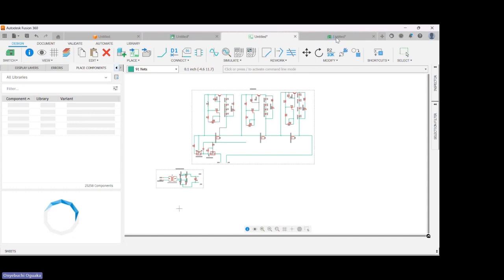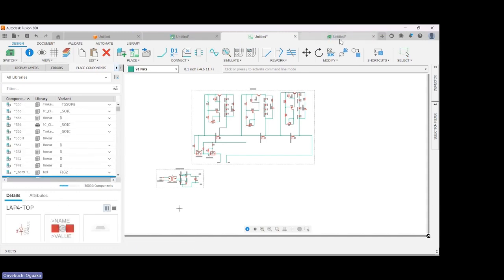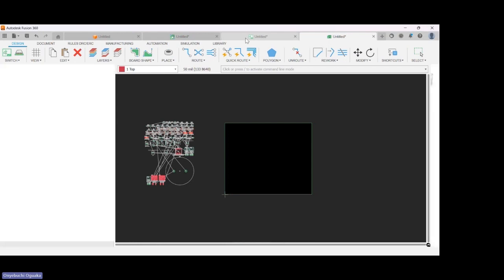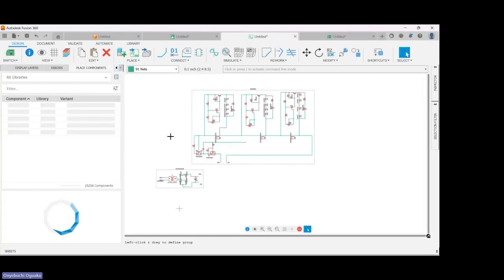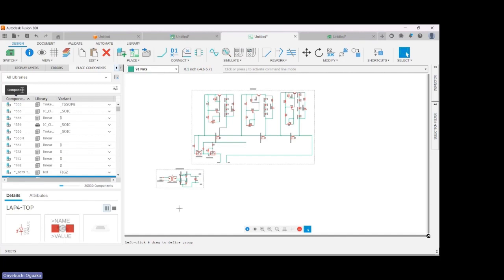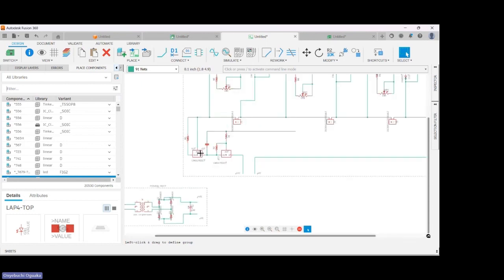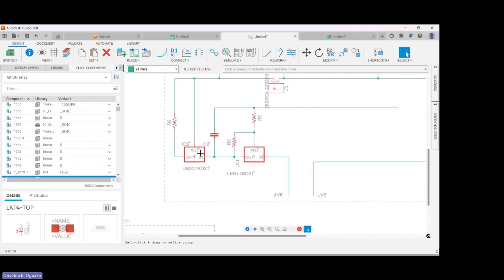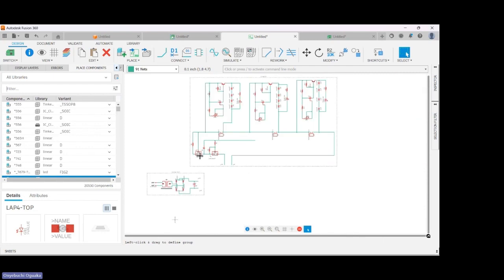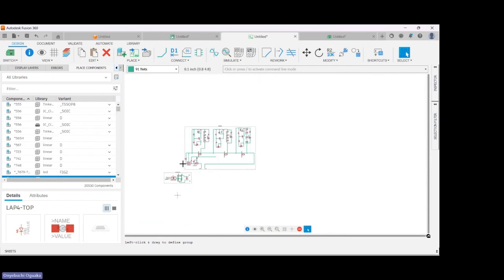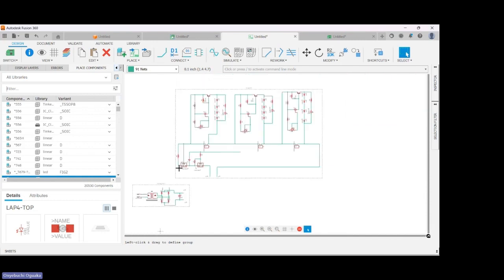Oh, and I think we forgot something, so you can switch over. Now, this is the PCB that when we pushed, this file got created. You can see my cursor. This file got created automatically, so you can switch in between. So we forgot to include a heatsink because there is no fan in this circuit, and these linear voltage regulators, this LM317, though this is not the precise voltage regulator to be used in the circuit, for reference for this tutorial, we are going to be using this.